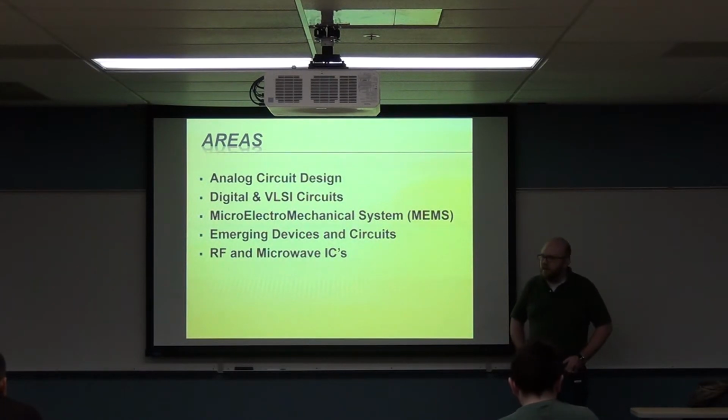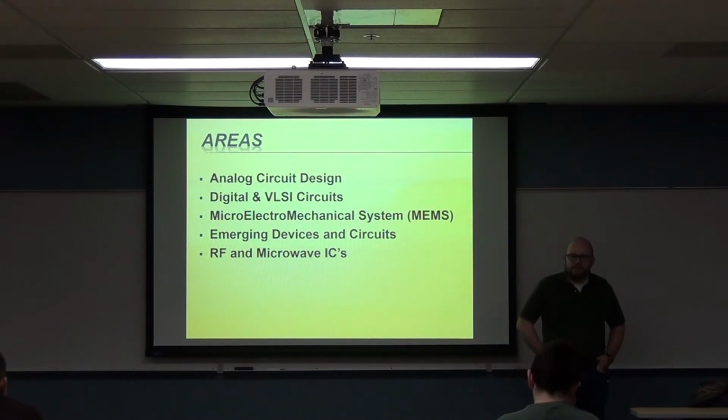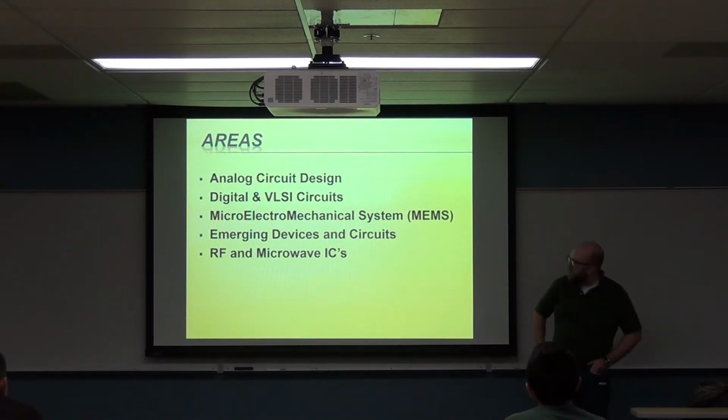If I'm running an antenna, I might need to work at the gigahertz range and provide powers in the watt range, but transistors don't like doing that. It's unfortunate. The total power budget for my 3mm by 3mm chip is maybe 2 watts, but in RF I need transistors that transmit in the watt range. There's a whole bunch of interesting questions there, and it's a lot of fun.